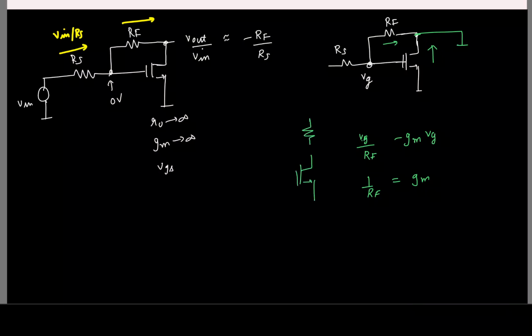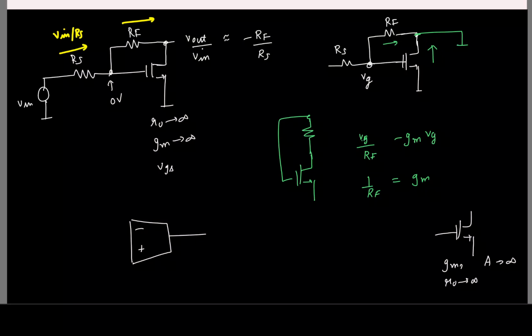You had something like this. So essentially, I'm redrawing the same thing again and again. And this is actually one difference between a VCCS and a VCVS. Let us say this transistor as such didn't have any R0. Then what is the intrinsic gain of this guy? It has finite gm and infinite R0. Gain is actually infinity. But even though the gain of the transistor itself is infinity, this is a VCCS, so I'll model it like this.